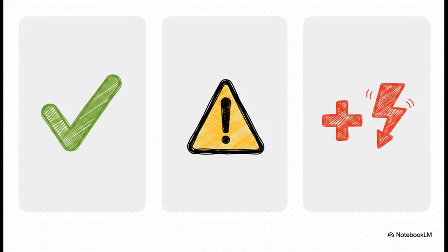But if things shift into a warning state, the display aggressively grabs your attention. If the battery temperature hits between 50 and 65 degrees Celsius, the digits turn yellow. Exceeds 65 degrees, they instantly snap to red. Plus, a literal plus sign appears next to the load digits to explicitly warn you of a DC power source overload. It's a highly visual, color-coded safety net.